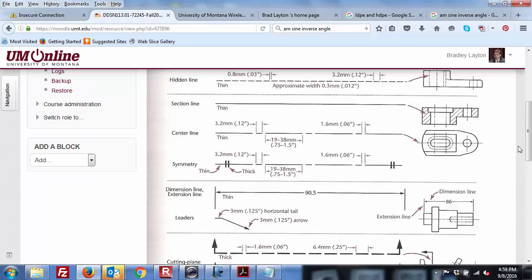Dimension line, it's a little thinner, and the whole point of the dimension line is it's not taking center stage. You can see that these thick lines are still the outline of the main part. Dimension line has a portion that's missing or blanked or whited out. In general, and there's different techniques for doing this. In general, you might make that dimension line first, and then erase wherever the dimension is going to go in. Sometimes a little easier, or if you want to skip the erasing part, draw this in, write your numbers in, and then continue with the line.